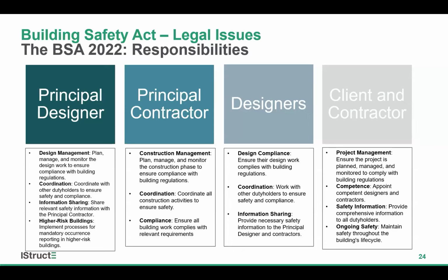It introduces the duty of coordination, so the duty to coordinate with other duty holders to ensure safety and compliance, and helping and advising the client in bringing together the pre-construction information and providing information to other designers and contractors so that they can carry out their duties. The duty of coordination also entails working with other designers on the project to eliminate foreseeable health and safety risks to anyone affected by the work, or indeed to take steps to reduce or control those risks.